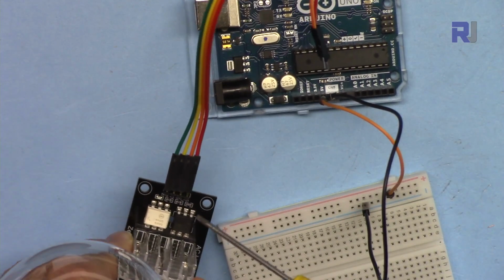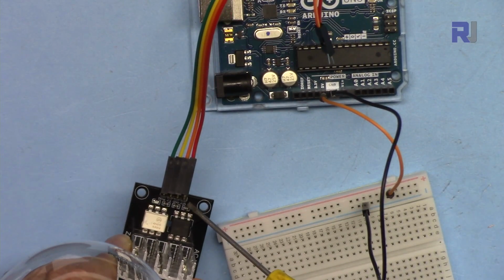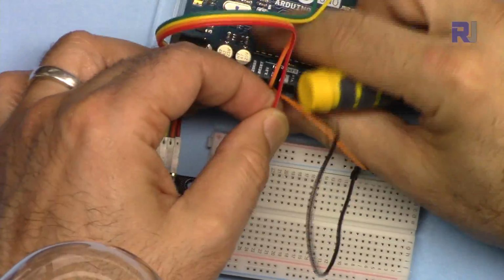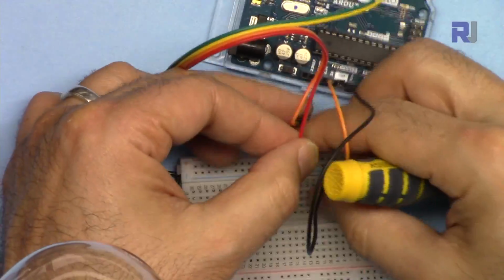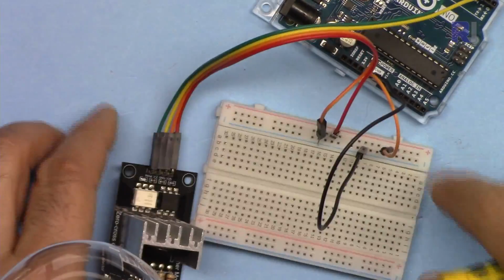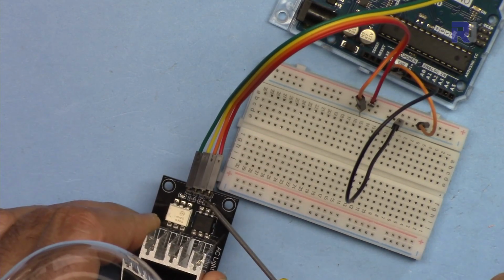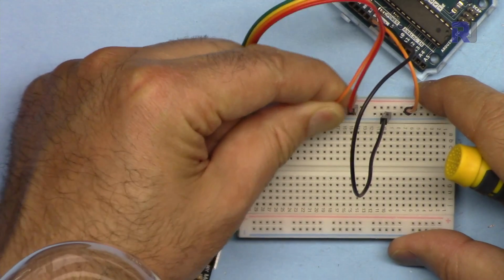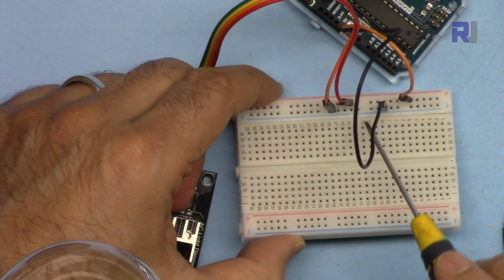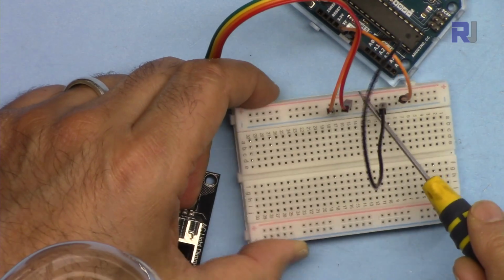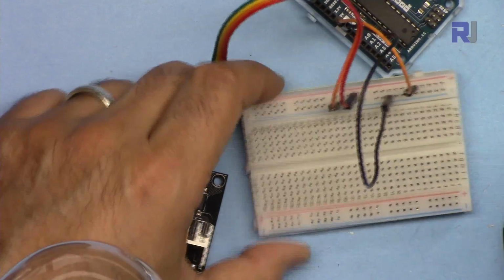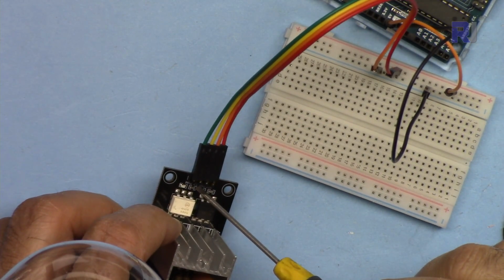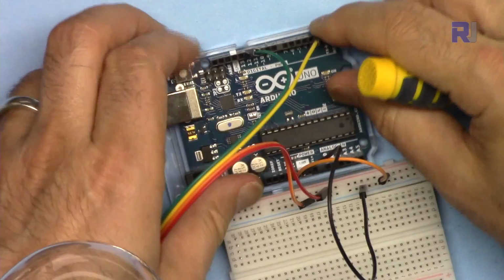And here, these wires, it says VCC. This will be connected to 5 volts. This red, I'm connecting it to this 5 volts. The second pin is here, ground. This is connected to the ground, to this blue, and the other one is connected to 5 volts, as you can see. And then we have here zero crossing. This yellow is connected to pin 2.